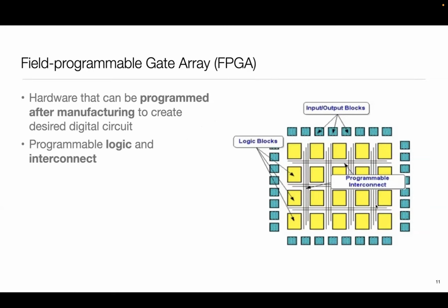You can think of these macro blocks as not being as powerful as processors, generally speaking, although in some cases you may have a processor sitting there. They're really simple, but not as simple as a low-level AND or OR operation. They can still do something substantive. And the wiring is already laid out, usually in some regular pattern. A lot of people spend time on what topologies to look at, but the wiring is programmable.